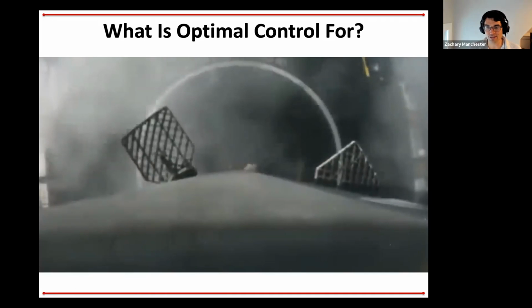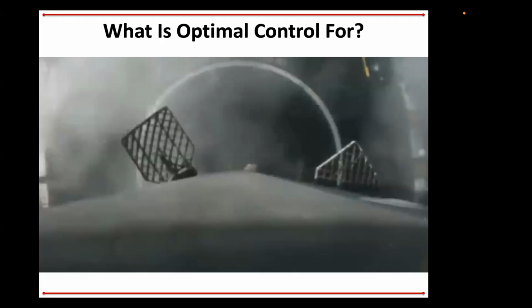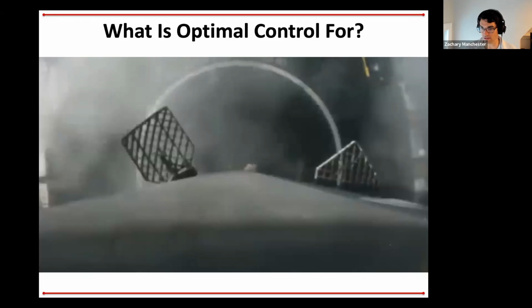Yeah, so as a lot of the stock stuff is these days, this is convex model predictive control with a lot of secret sauce and robust low-level tracking control stuff. There's been actually a lot of progress in what's called the rocket soft landing problem in the last 10 or 15 years. There have been some major breakthroughs and some seminal results on how to reformulate this rocket landing problem as a convex optimization problem. This is how we land on Mars and things like that, which is pretty cool.